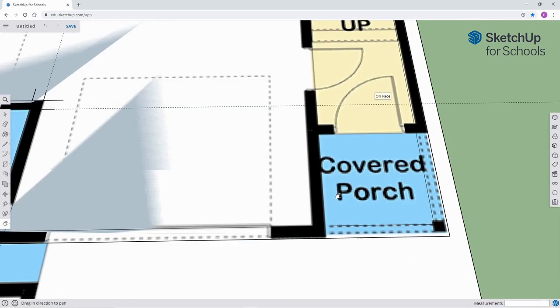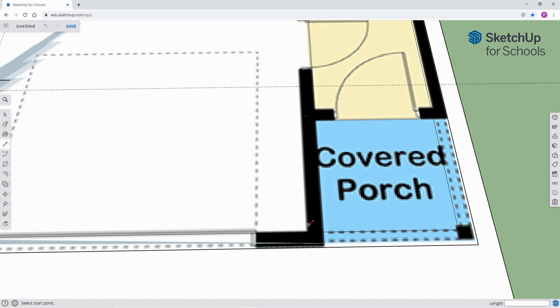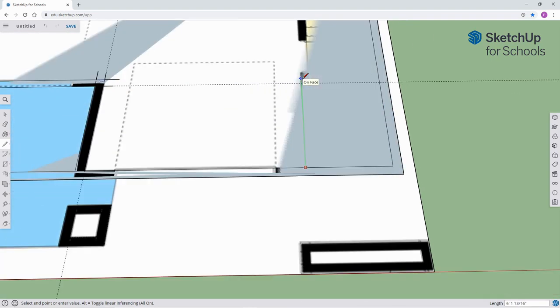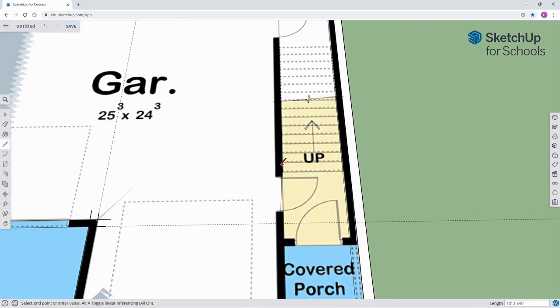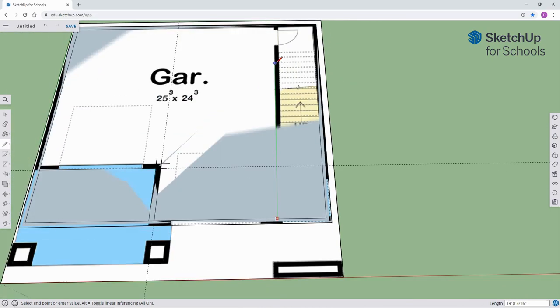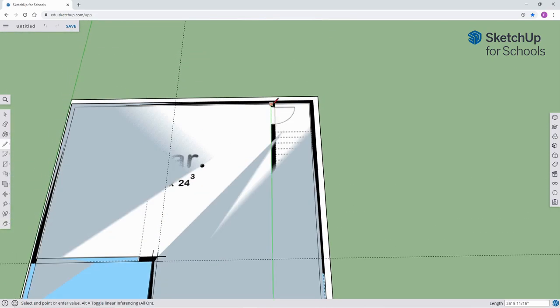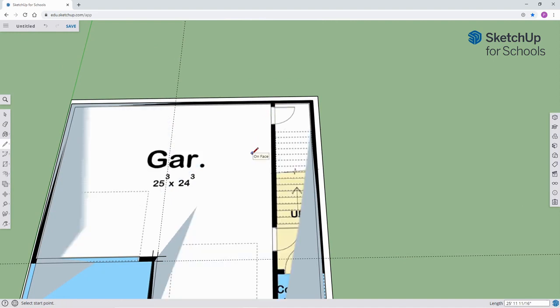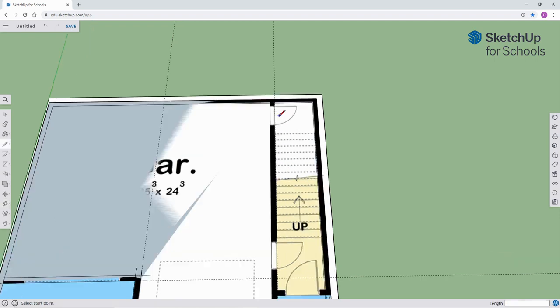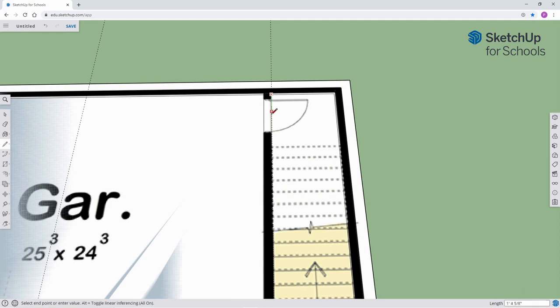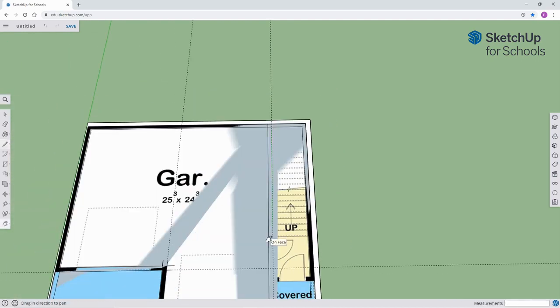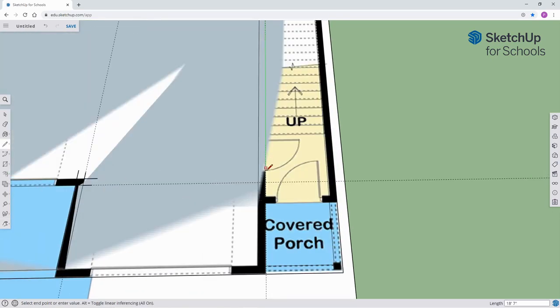All right, moving over to the other side. Working slowly. Again, with a focus on precision. I will extend this line all the way up to the top. Here, I have pulled up the guide tool. Now, I am typing 6 inches. I will then bring up the line tool and trace over my guideline, thus ensuring a 6-inch width for this interior wall.